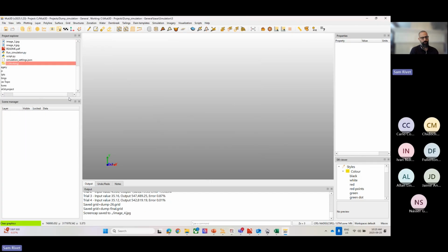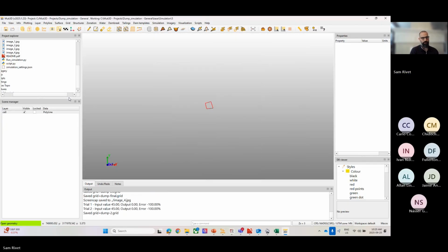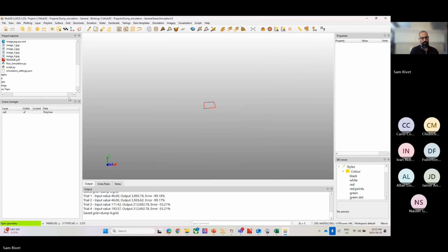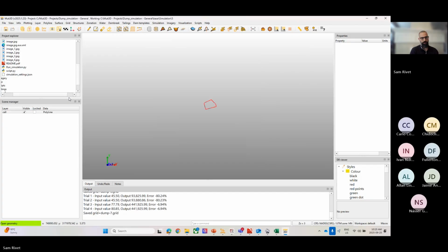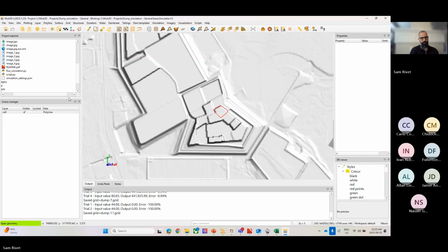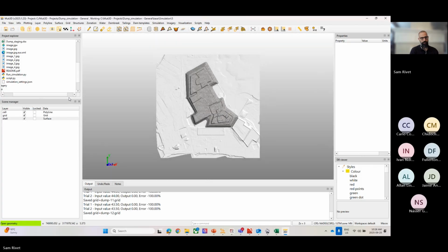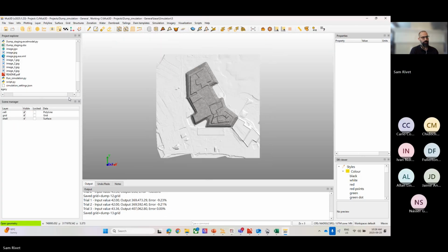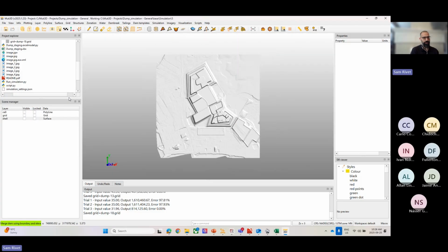So once again, just creating that merge grid, the visual, cut fill map, save it, move on to period 5. So always referring back to that final design, same line work, just progressively building up each cell as you allocate volume to it.